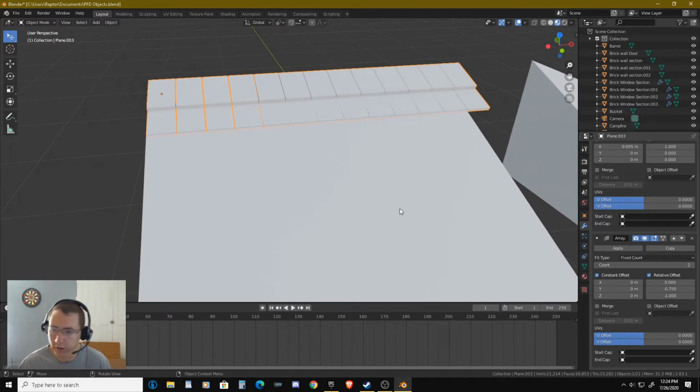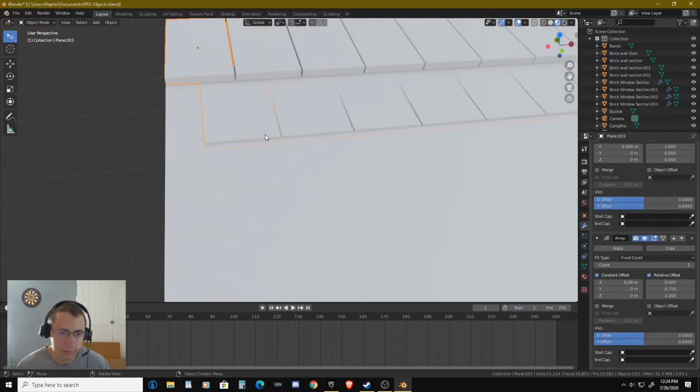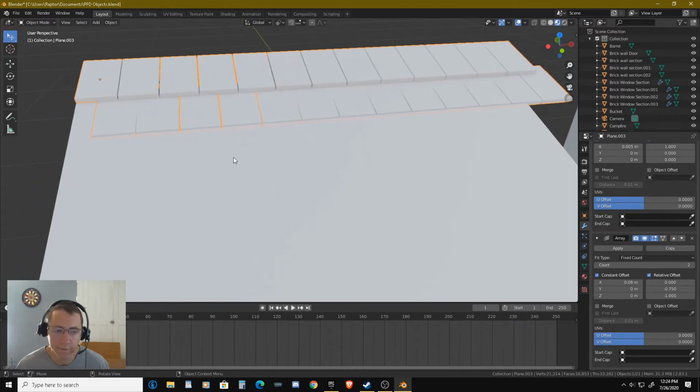And then we're also going to set this to have a relative offset on the x-axis of 0.5. Oh no. That's going to be, we'll set this one to 0. And we'll set this one to 0.5. No, that's a little bit too high. So let's bring this down until it's about right in the middle. There we go. 0.8 meters. Perfect. Okay. And then we're going to go ahead. Actually, let's do this to negative.